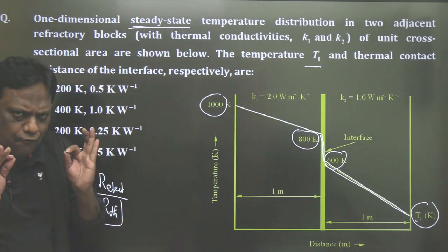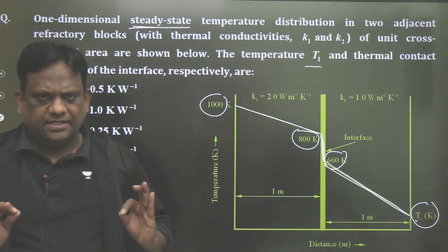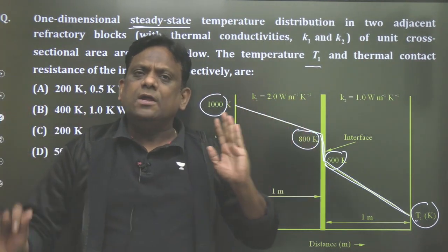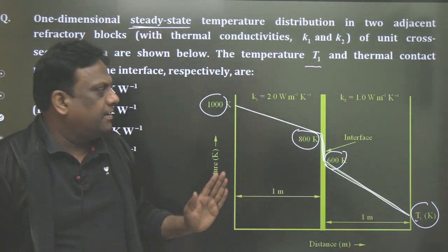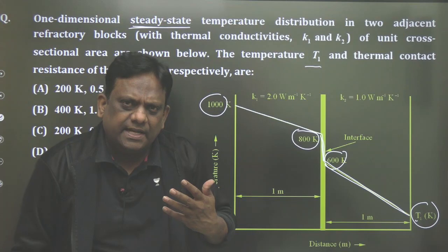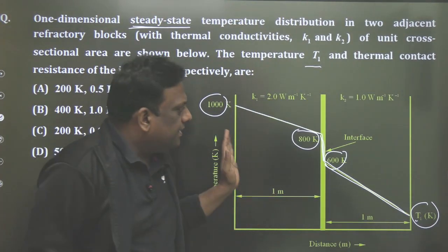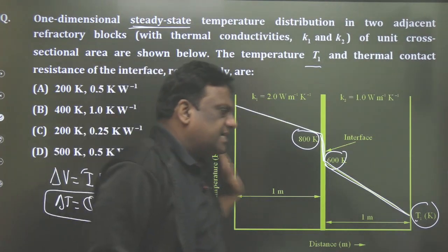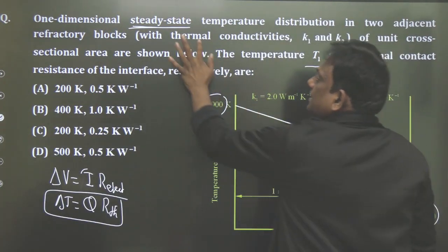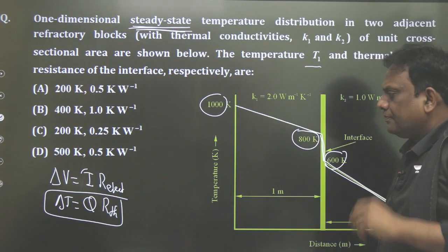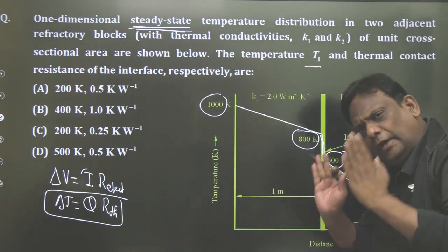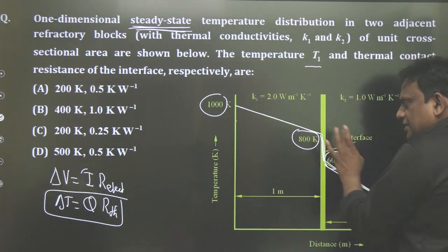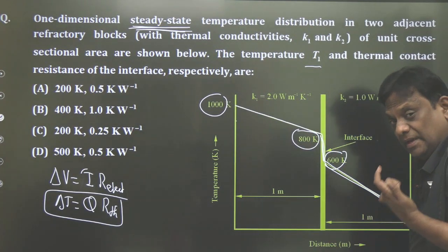Wonderful. So whenever you come across such questions, the first and foremost thing is to calculate the heat transfer. Why are we calculating heat transfer? Because that will help us calculate different parameters. Once I calculate heat transfer, at every section the heat transfer will be the same because it is steady state. So you can apply it to any section. For example, I'll apply between these two sections.